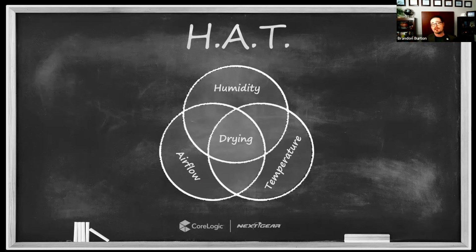But if we don't have airflow on the wet surfaces, then that environment is actually perfectly conducive to mold growth, because mold occurs with the humidity at the surface, right? And without air movement, that low humidity that we observe three to four feet above the floor is irrelevant, right? That humidity is not the humidity that is preventing damage or causing drying to occur. It is the humidity that is in contact with the building materials that's doing the work.